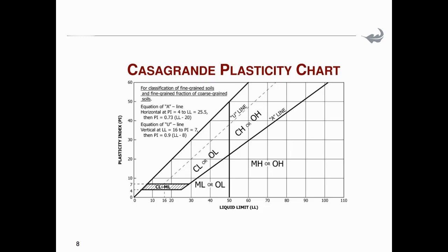So depending on the plasticity index, the PI or IP, versus the liquid limit, your soil can then be classified on this chart and you have a good description. So CH, for instance, would be an active clay, or a clay with a high percentage of active material, etc.